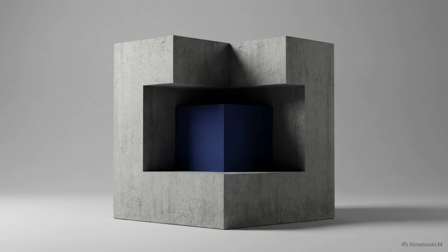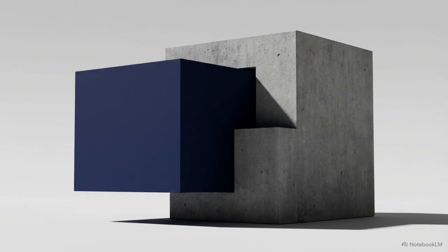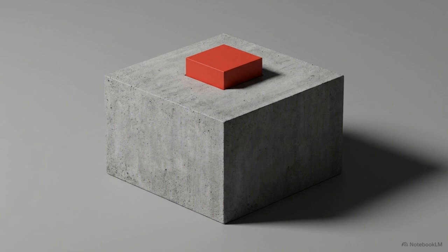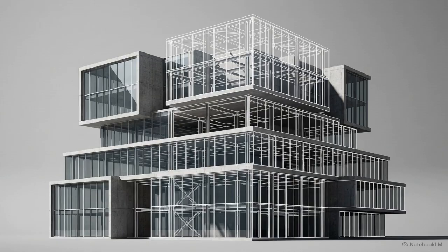To create intimate spatial relationships, we nest a smaller volume completely inside the primary mass. By shifting it outward, we overlap the two, resulting in a partial intersection. We intersect by pushing a distinct, long rectangular volume entirely through the primary mass. Conversely, we embed a smaller shape by sinking it flush into the exterior surface. Strategically adding and transforming material allows architects to scale up a building while strictly maintaining its underlying structural logic.